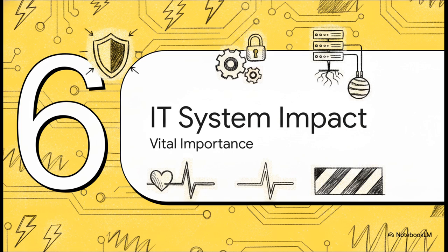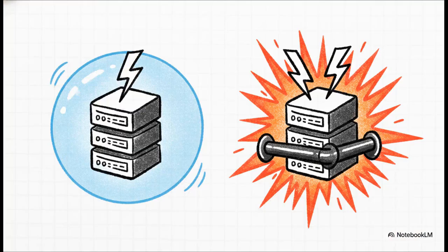All right, final section, Section 6, IT grounding system impact. Let's pivot to a real-world application where this theory meets critical safety standards. In isolated, ungrounded IT systems, this distinction isn't just theory, it's vital for system survival. A first ground fault is usually tolerated because the system doesn't have a direct path to ground, so it can just keep running safely. And that is exactly why we rely on installation monitoring devices, or IMDs, to alert us to that very first fault. But if a second fault occurs on a different phase before we can fix the first one and a metallic path links them, it creates a catastrophic short circuit. The presence of those metallic return paths makes understanding this distinction vitally important for protecting your systems.